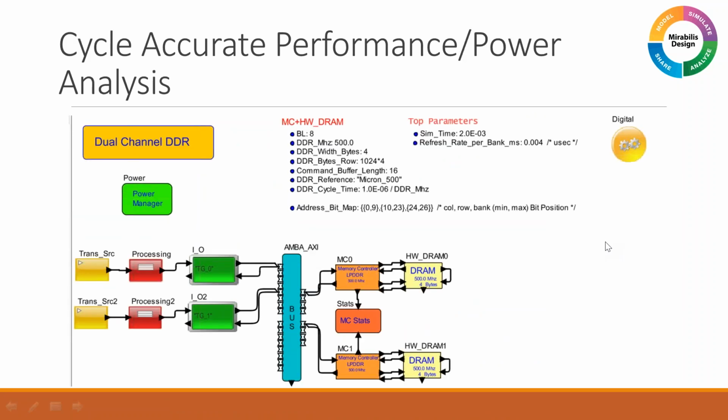Now, one of the key things in any design is looking at the hardware software related to memory access, because your read-write latency has a huge impact on the performance of your system. So even if your pipeline does very well in terms of execution, your read-write latency can cause a huge disruption or huge slowdown in your actual application behavior.